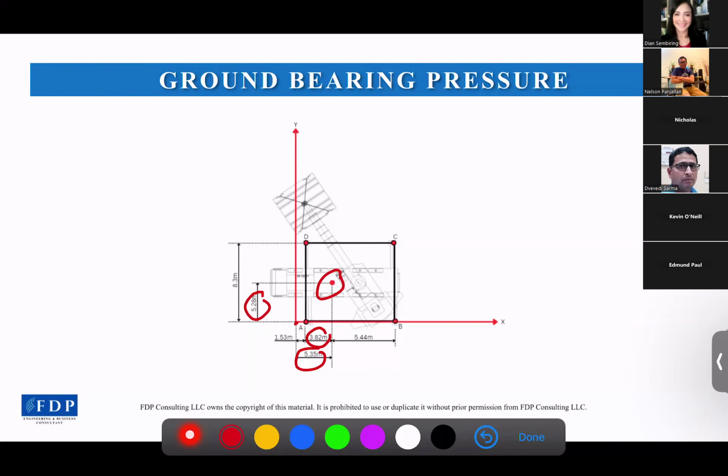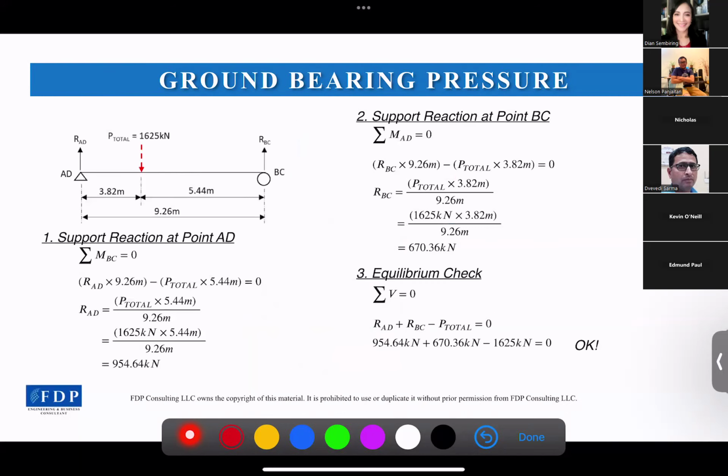Now we try to find out the reaction of each outrigger. I'm assuming that this crane is rigid, meaning that the flexion of the outrigger frame will be ignored in this calculation. So that we could calculate this by using determinate static structure analysis. First, we will distribute the load to one pair of sides.